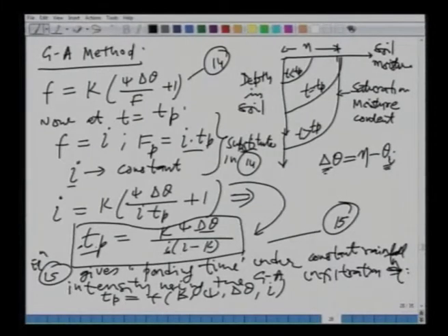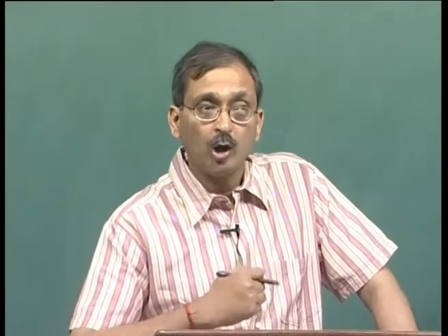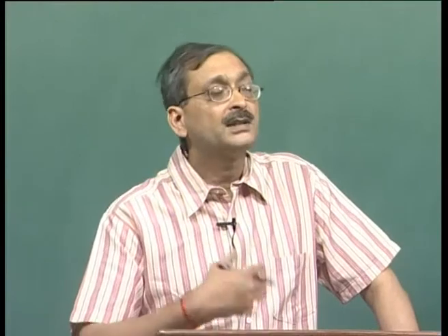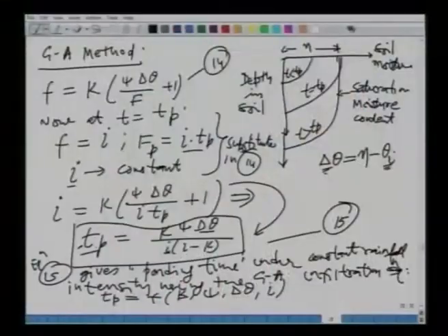What about the rainfall intensity? Consider a catchment when rain is falling at a very high rate as compared to another time when the rain is falling at a smaller rate. The slower rainfall will have the higher ponding time. The higher the rate of rainfall, the more quickly the water will pond and the time to ponding will be small. So, it is easy to see that the equation which we have derived intuitively makes sense.